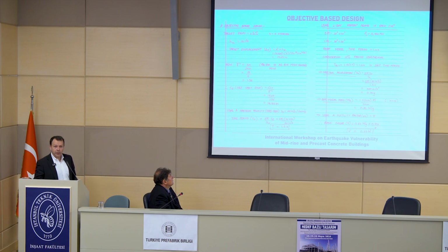Bob yesterday joked that Chopra had written this equation about 100 years ago. It's probably close to 50, but this is your participation factor to account for the mode shapes. And so 1.36 for gamma. And from there, you establish your objective spectral displacement, which is just the target divided by gamma. And so in this case would be 14.45 inches. I have these numbers summarized in metric later as well.